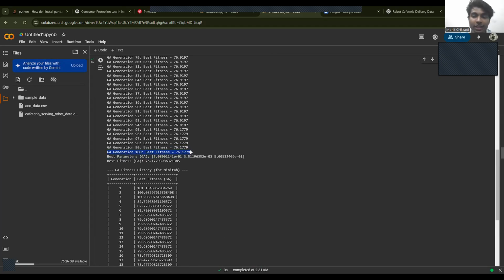That is the number of iterations the generation or the evolution worked, and we have also received the results. So the best fit parameters were 54.1, 0.05 and 0.5, and the best fitness that the GA gave was 85. So with this GA, we found the parameters that significantly improved the robot's performance, reducing the tilt angle and deviation while maintaining fast and stable turns.